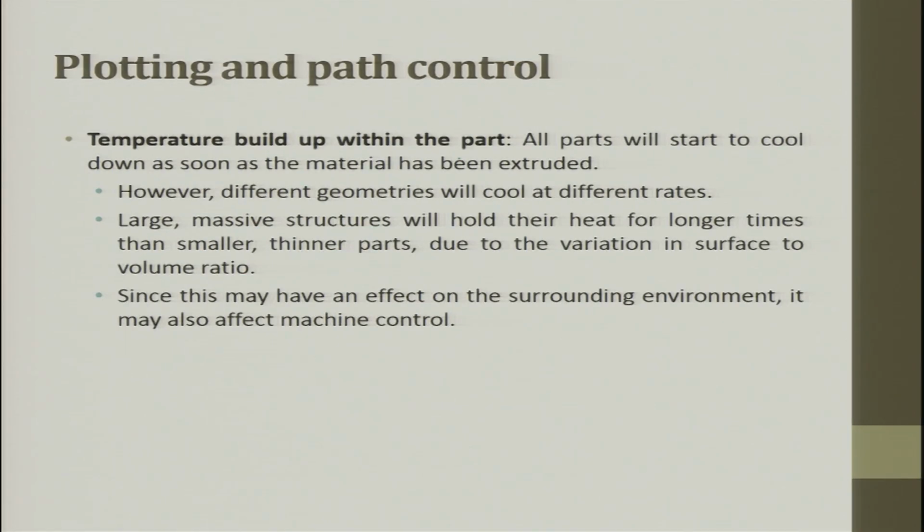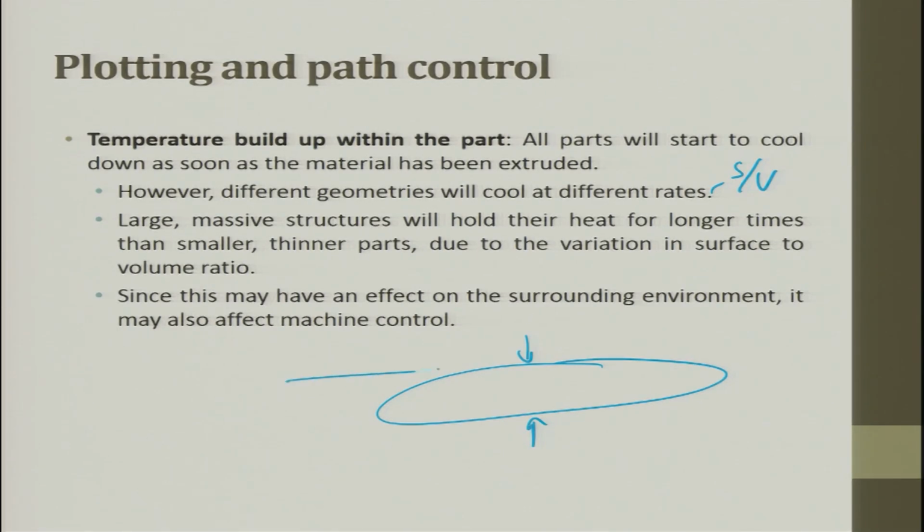The temperature built within the part: all parts will start to cool down as soon as the material comes out of the extrusion. However, different geometries will cool at different rates, because it depends on the surface to volume ratio. If there is a large surface and this is height, and this is dia, fine.